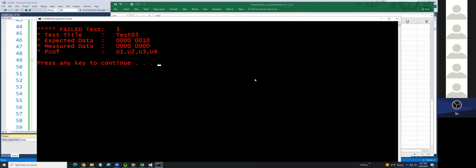Using the DMM, I want you to measure at that pin number to see what logic it has. If you get a 0, then we try to find out why it is 0 in order to fix it. That is what we call troubleshooting.